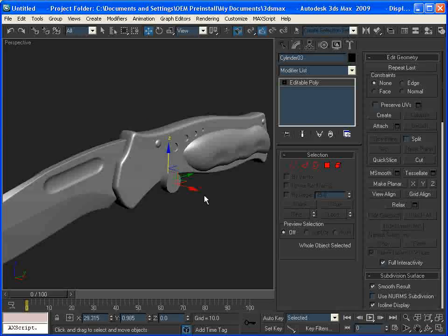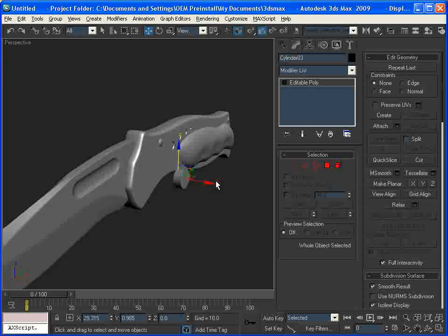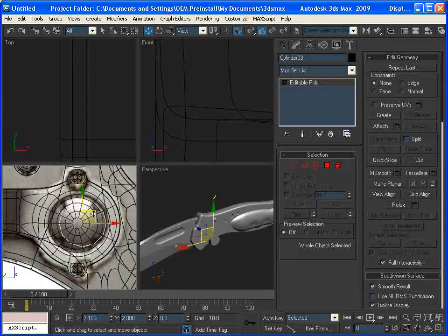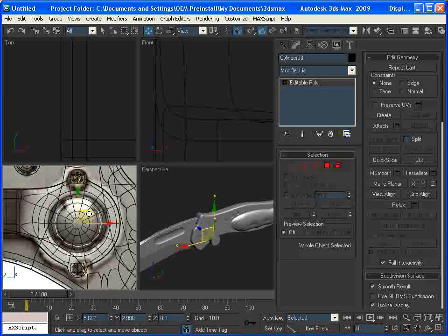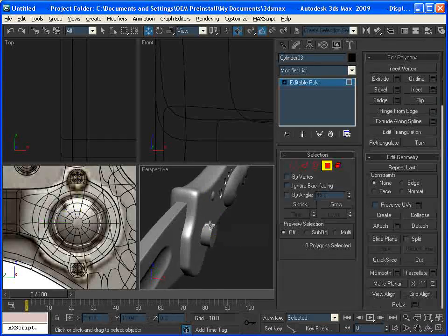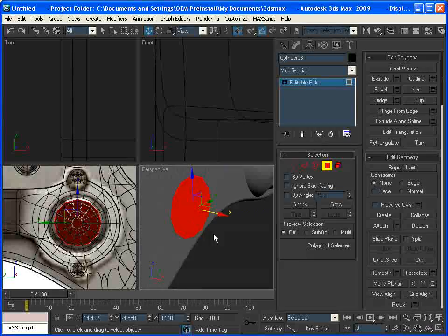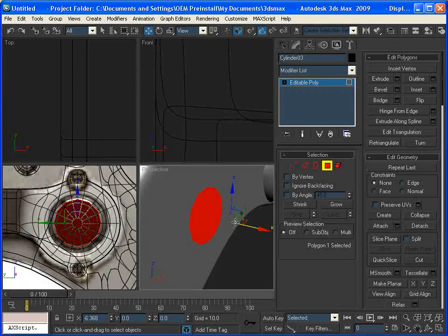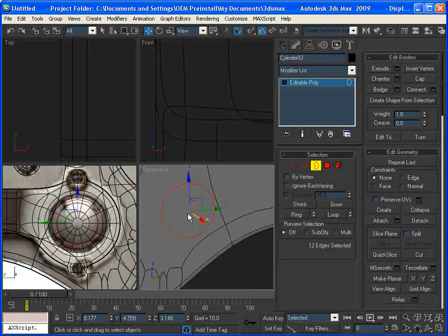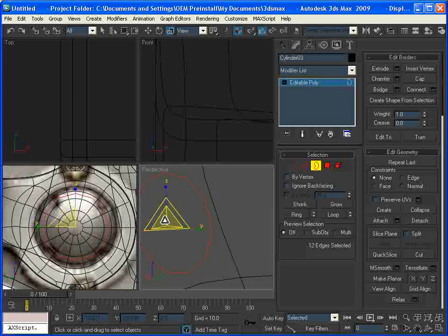Basically, especially with high poly stuff, I guess, just because it stands out more, when you're making a high poly model, you've got to remember that the only reason you're making it is for the normal map baking, and occlusion or whatever, but primarily the normal map baking. And to that end, you've got to be thinking, what am I getting out of this normal map? How can I maximize the returns I get for all this effort that I'm putting in? Because you're basically modeling the same thing two times. The first time high poly, and then the second time, of course, low poly.